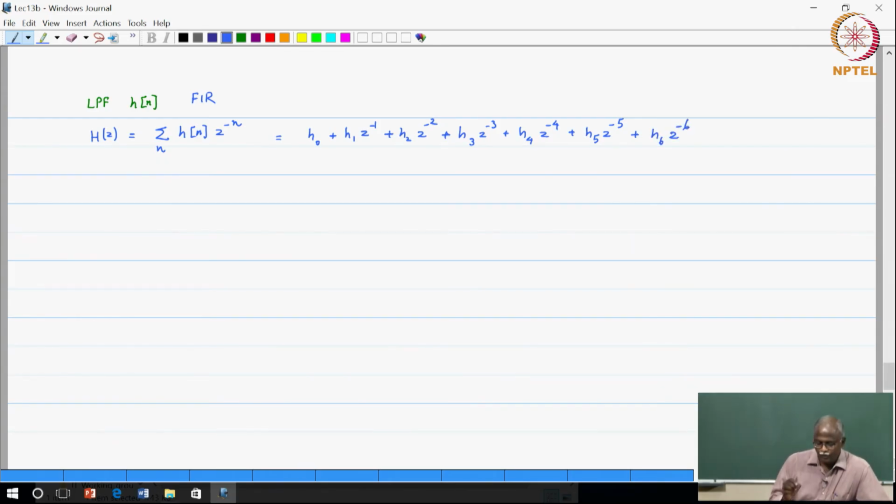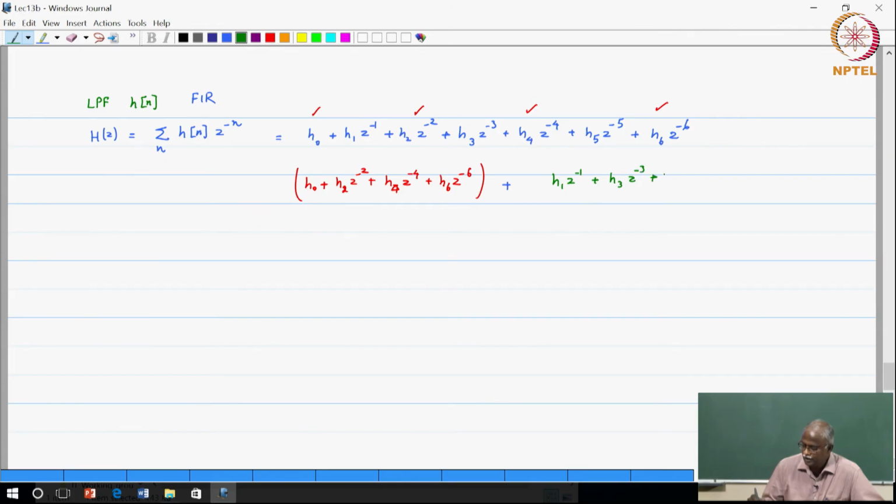Now, if I were to group these even terms of the impulse response, I would get h0 plus h2 z power minus 2 plus h4 z power minus 4 plus h6 z power minus 6, plus z inverse times h1 plus h3 z power minus 2 plus h5 z power minus 4.